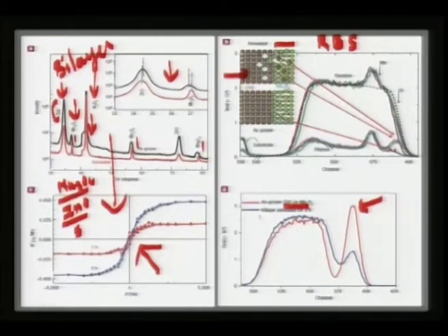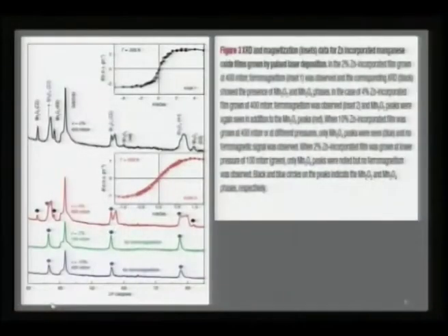Now, if you anneal this compound for 9 hours, you can see the zinc proportion going down considerably. What does it mean? It is not the reverse transport, that is manganese going into zinc oxide; it is the zinc which is diffusing into the manganese oxide layer. So, this is a very handy proof, and to support this, this group also did another experiment.